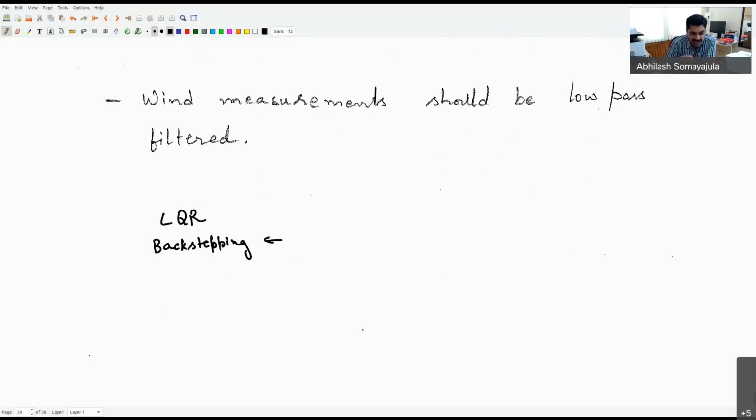Or you could have a sliding mode control where we are going to say that I don't care about the current dynamics of the system, but I'm going to force it to follow a certain dynamics where things are well mannered. But the problem with all of these different nonlinear controllers is that they are a little harder to implement, and computationally a little more expensive.